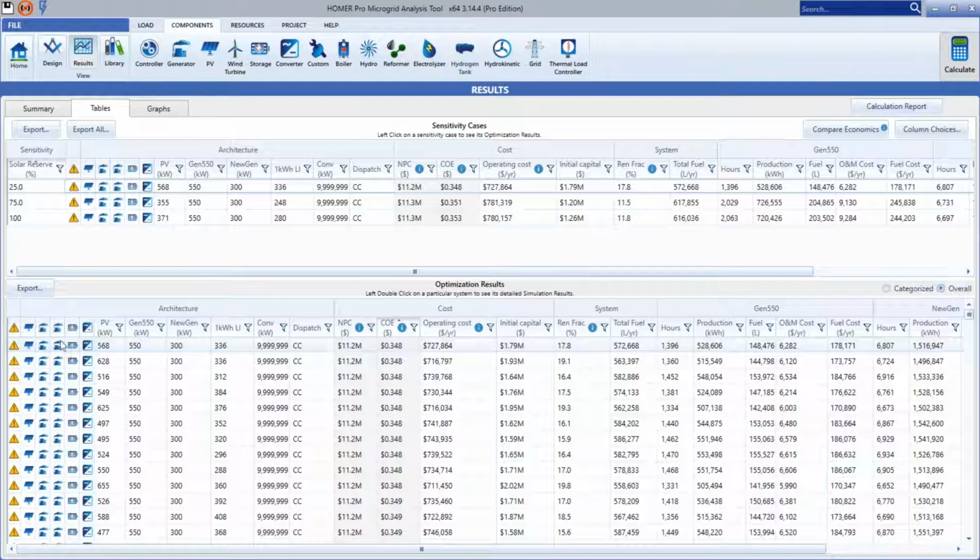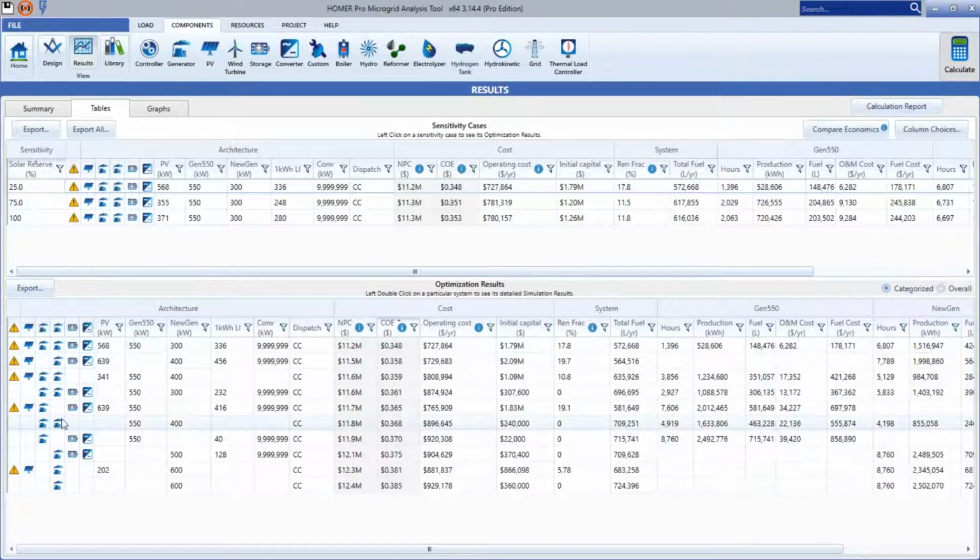Peter, would you like to emphasize on this warning sign? Sure. And this goes especially to systems without batteries. That really limits the penetration level that you can have. And also systems with very small batteries. If you have a large enough battery, that can provide the stability.